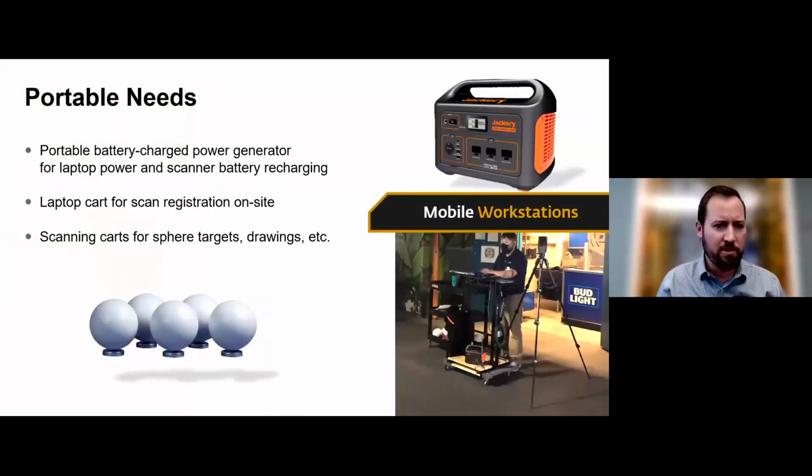We also knew portability would be a consideration and an issue, so we wanted to have power at all times. So we purchased a battery charged power generator. We had that on a laptop cart so that the laptop always had power on site. So the project manager who was coordinating access to areas could also be registering the scans that he received daily on site through that laptop cart.